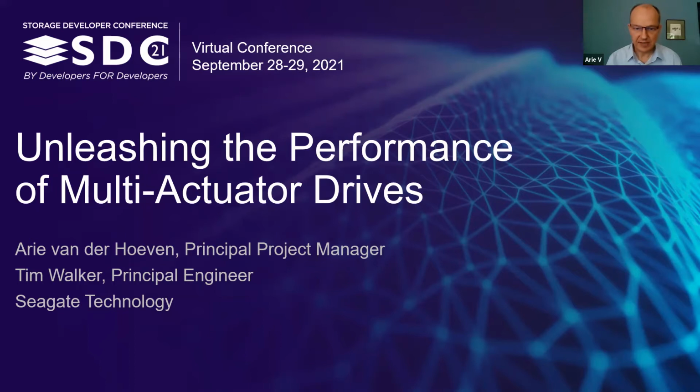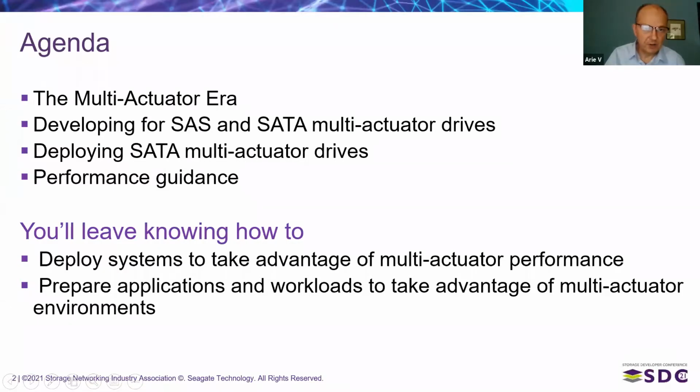Tim has spent many years in this type of topic, and the topic today is unleashing the performance of multi-actuator drives. Let's look at the agenda. We're going to start by looking at what we're calling the multi-actuator era. That's because we're getting to a point where drive sizes and areal densities are becoming so large that to achieve any kind of reasonable IOPS performance out of a device is going to eventually require multiple actuators. So we see that starting today, and we'll go into that more in this first section.